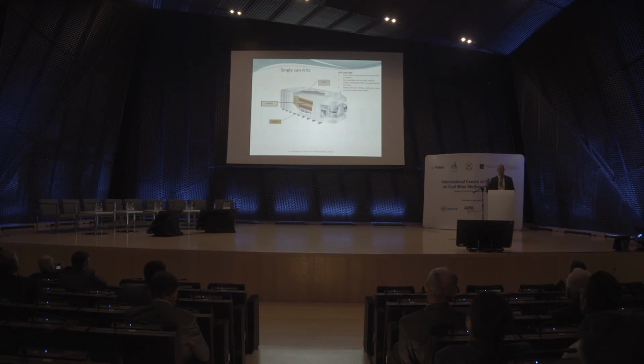The most simple description is that you have a very, very well insulated steel container. It's filled with a ceramic material like gravel. In the center, you have electrical heaters. You heat it up to 1,000 degrees C, then you start passing the ventilation air through the box. As the air comes to the center of the box, it will be at 1,000 degrees because you have very efficient heat transfer between the air and the media. Now, 1,000 degrees with oxygen present, of course, all the methane molecules will have oxidized.